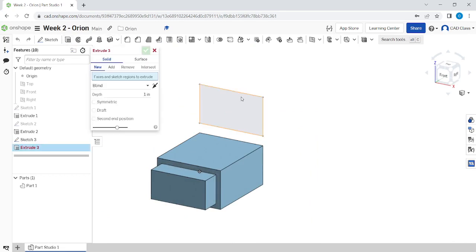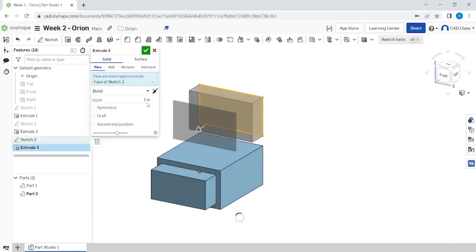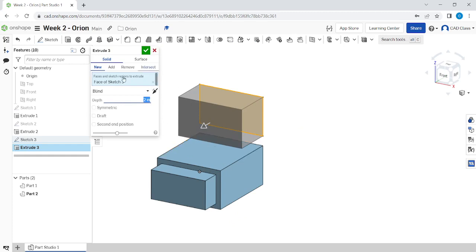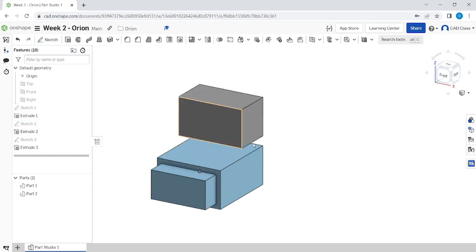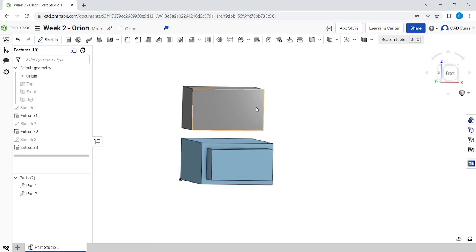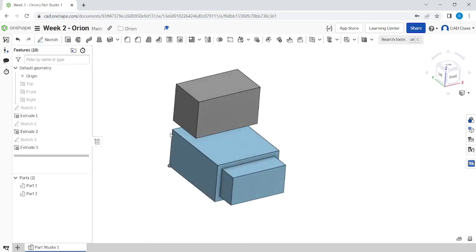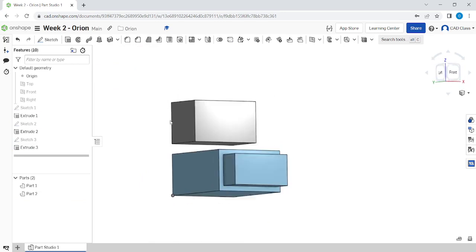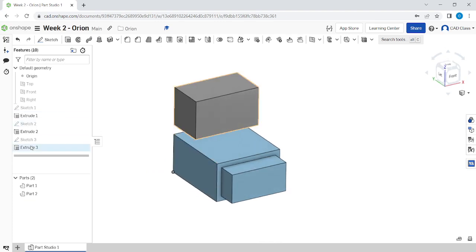Then we're going to finish the sketch. We're going to click the extrude tool. We're going to click the region. We're going to extrude it out 2 inches and press enter. I'm going to add a feature to this actually. So what I'm going to do now that I've created this is show the power of the parametric modeling tools here. You can see over here in the feature tree, everything that we've been doing shows up. And so I can go back to any of these items here and edit them after the fact.